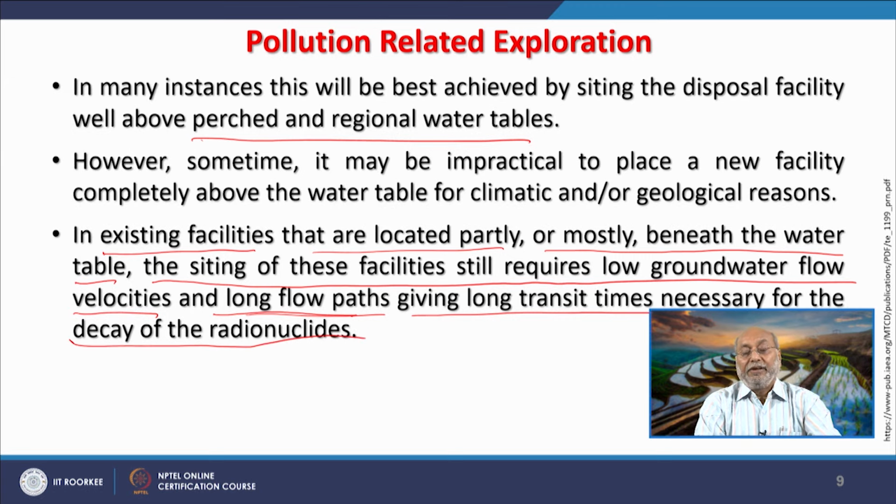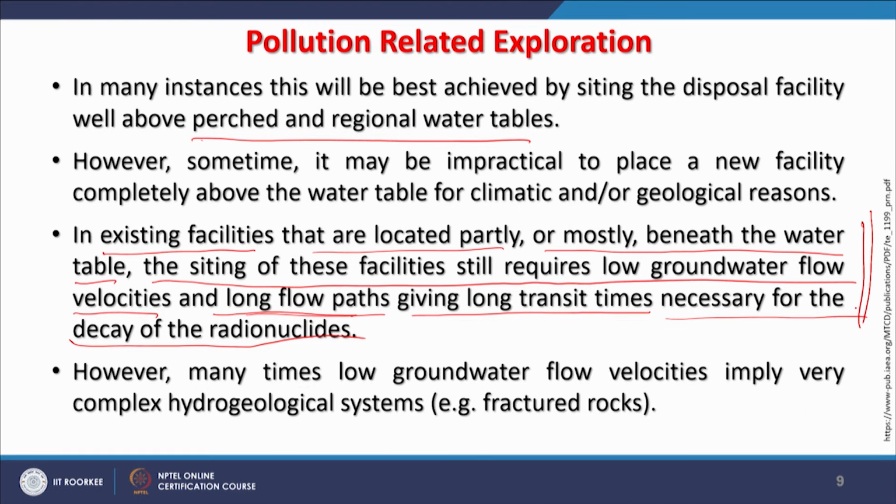Disposing nuclear waste and not harming our groundwater regime is another big problem, and that is also being addressed indirectly in this part which I have just discussed. Further, many times low groundwater flow velocities imply very complex hydrogeological systems, and in such cases hard rocks may be very good, because you only have a fractured or weathered part.